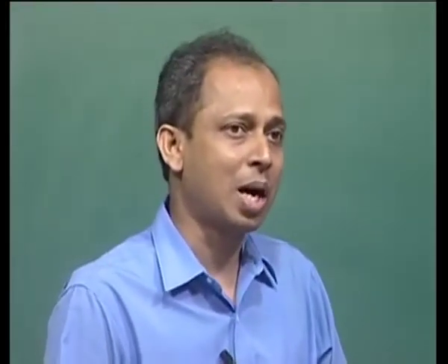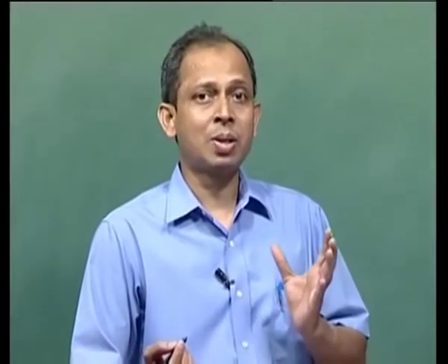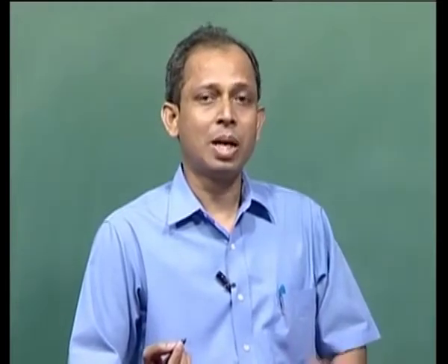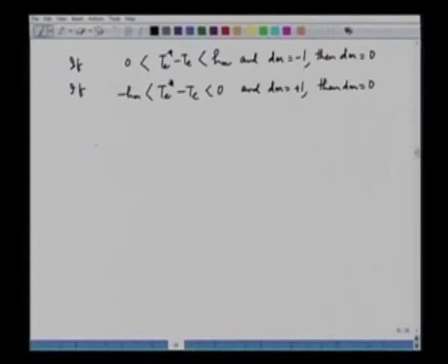Now how to increase the torque? The torque is increased by increasing the angle gamma SR. We know that gamma SR is the angle between the rotor flux and the stator flux, and if we increase gamma SR, the torque can be increased. And if you don't want to increase gamma SR, we can freeze the flux. We know that we have this equation that psi s is equal to Vs into delta t plus psi s at t equal to 0.